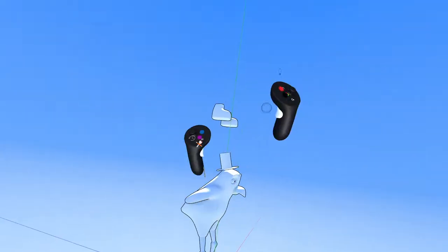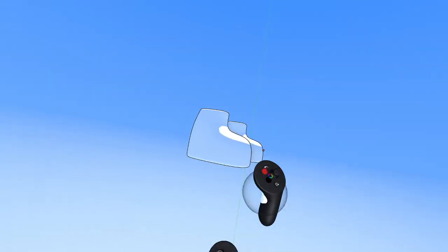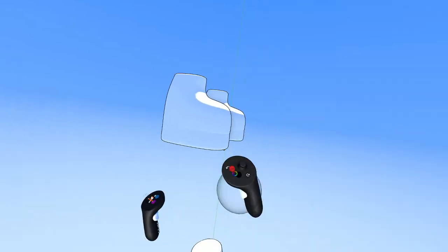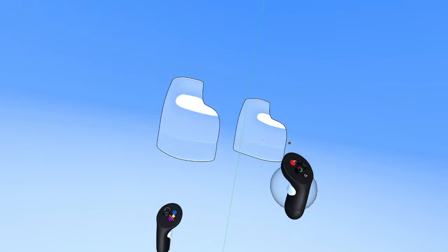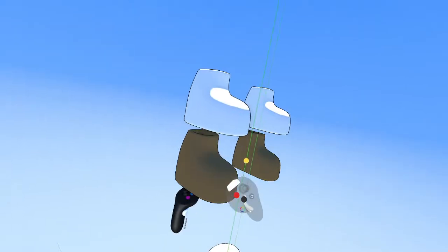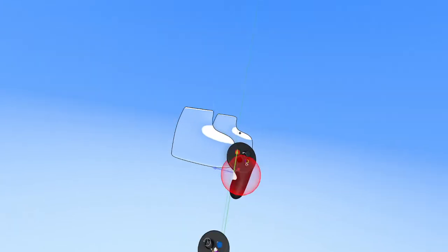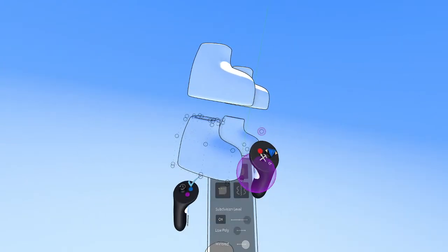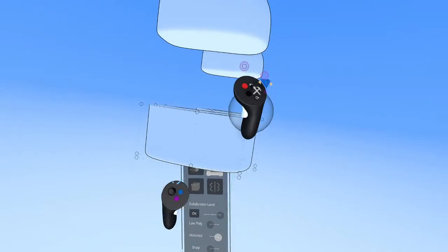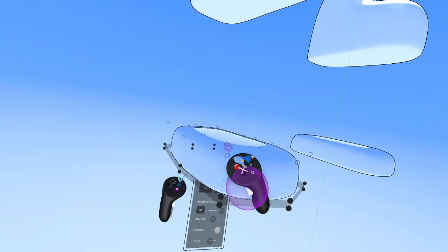Okay, so this is another decent thing to cover with Sub-D. We have these really simple boots, and they look good simply like this, but it might be good to add something like a sole to this. So we could just duplicate down that object and intersect it like this, and it's the same object, but it gives the indication of a sole for the shoe. Or what we can do is duplicate this down, delete all of that data on the top, shift this down, duplicate it in, and actually build the sole separately.